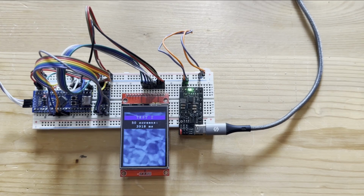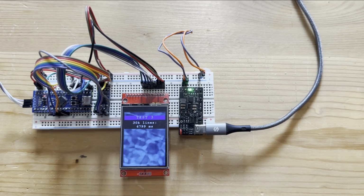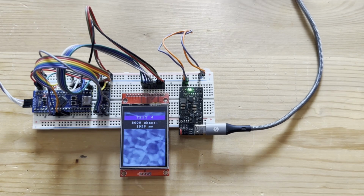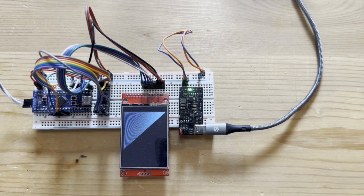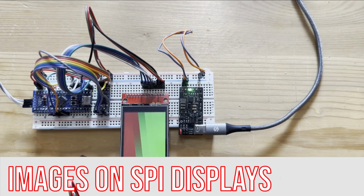As I already have done in other videos, I will use here for my test a system with a display. We will handle pictures to be drawn on the display, saving them on both internal and external SPI Flash. Handling images to draw, we have a need to store, read and move large or very large datasets, easily exceeding the microcontroller internal flash size. So, having in mind that all we will do here we could apply to any other data structure, let's use an external loader handling images in a CubeIDE project.